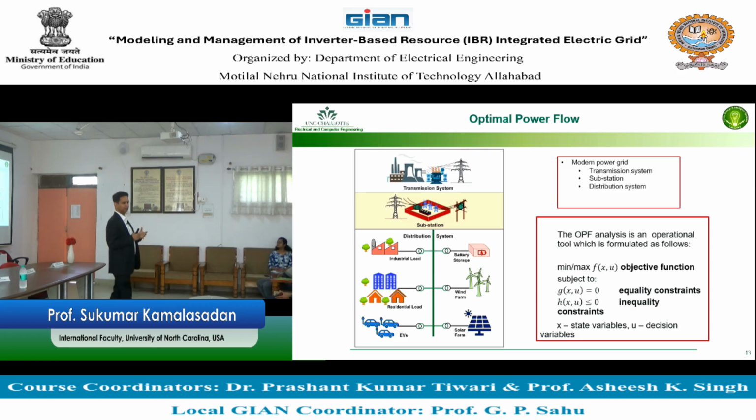So the input U goes into the plant, and the plant output is basically the state variables. Similarly, in here, the state variables are represented as X. In X dot equal to AX plus BU, what is U? Input variable, right? What is X? State variable, and the output is represented as Y. Easy. So Y equal to CX plus DU, that kind of form which you have. Now in the optimization world, state variables are X and the decision variable is represented as U.